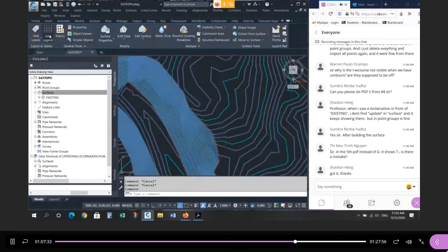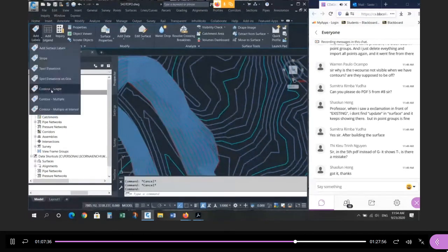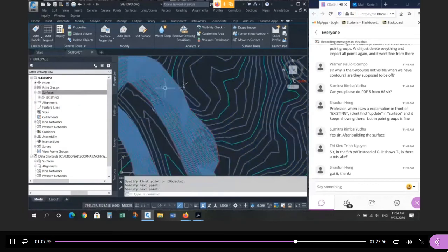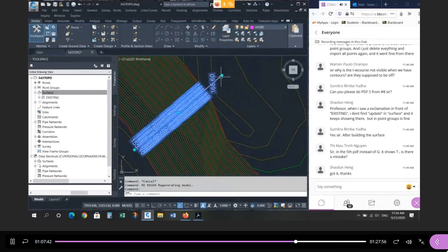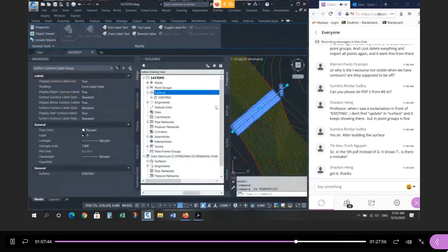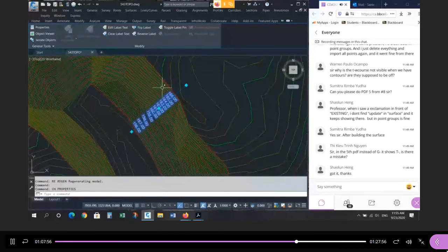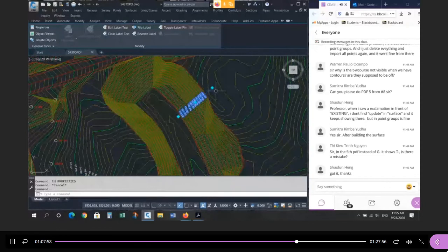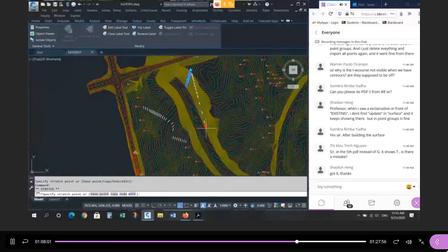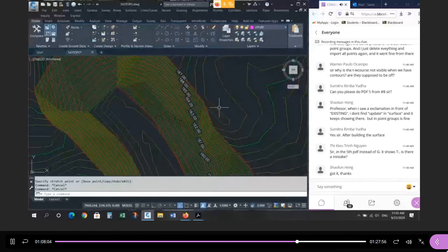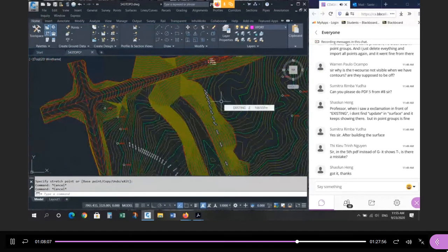And if you label a steep area, everything's going to be on top of each other. You can't read anything. In this particular case, if it's steep, if it's tight density, turn off the line always, and then turn off the visibility of the minor contours. Only label the major contours. And then that'll give you a little more space. And if they're still crowded, in this case, I'll make an exception. Instead of going perpendicular, I'll go on a slight angle, and that'll spread them out. That'll be a little easier to read. Okay. And these are just artistic presentation techniques that I'm giving you tips about.